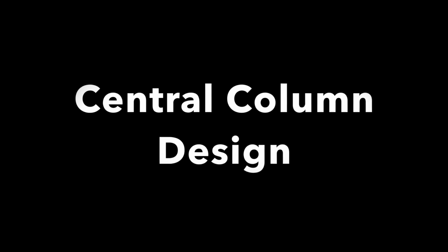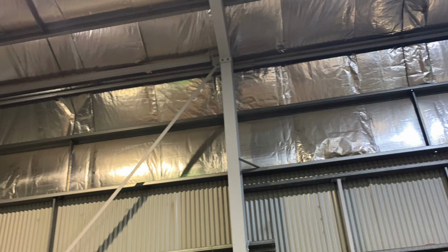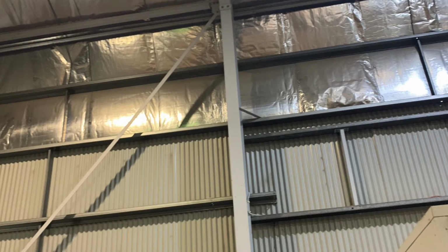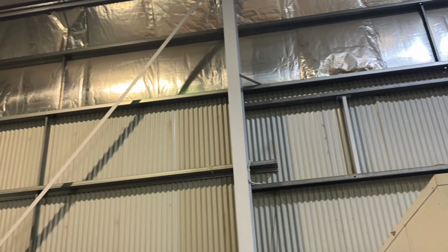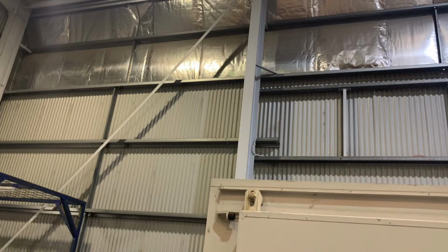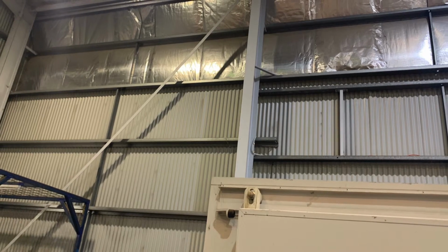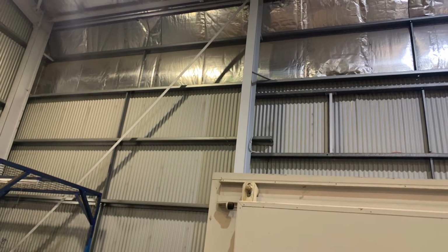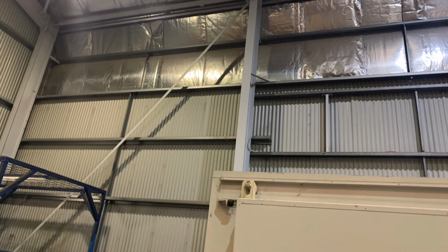A column is a vertical member which transfers the loads from the above members down to the foundation of the structure. Columns support the ceiling above and therefore allow the span distance for the members above the ceiling to be significantly increased if designed accurately. Compressive axial loads are carried down through the column members from the pin connections between the beams and the columns.